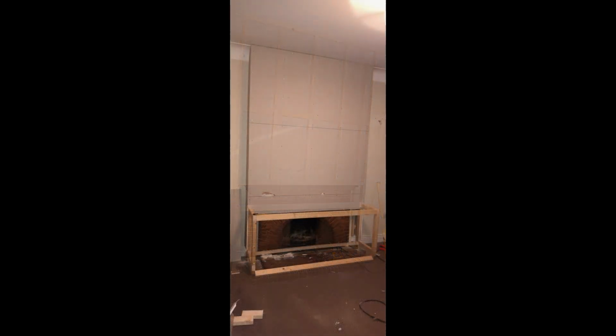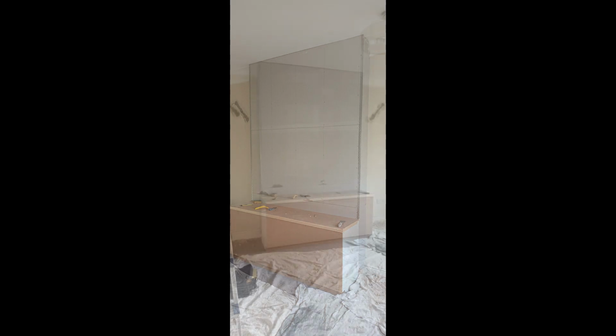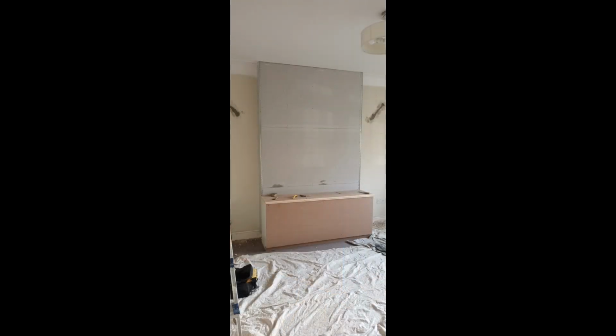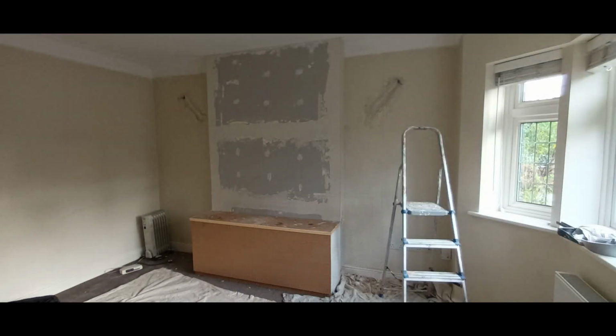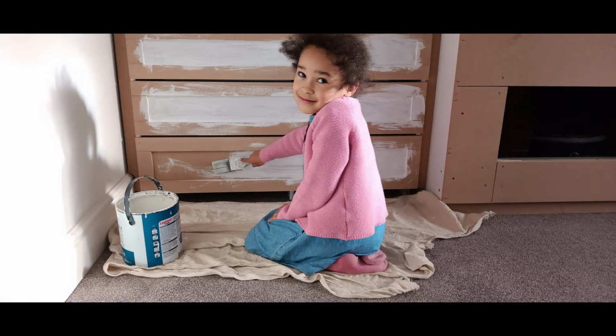Once your stud framework is up, cover it with 12.5mm plasterboard, get it nice and tight, and screw down nice and tight. Again, angle beads, and the angle beads are on, the projection is on, the base bit is on, and MDF is covering. You can see we're starting to make good progress. We've also run the lights in, and got some cheap labour with Darcy helping out again. She's always helping out, which is an absolute bonus for anyone working on the place.